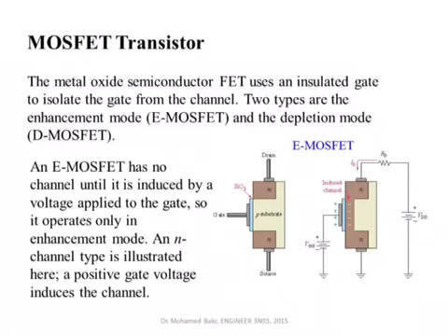So this device effectively has 4 electrodes: the drain, the source, the gate, and then the substrate. This substrate here, I will show you later, is usually connected to the source. We usually don't take it into account, but in some other applications, they simply connect an electrode here, another electrode here, and then they can use it as a 4-terminal device. But for this course, we'll assume that this one is connected to the source.